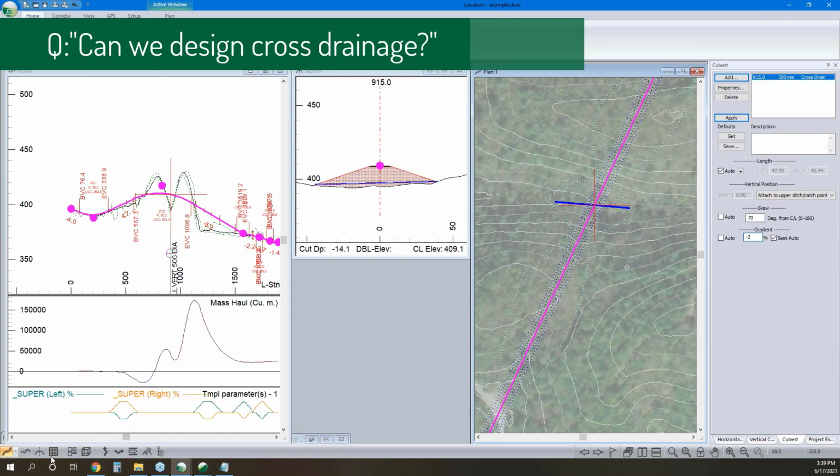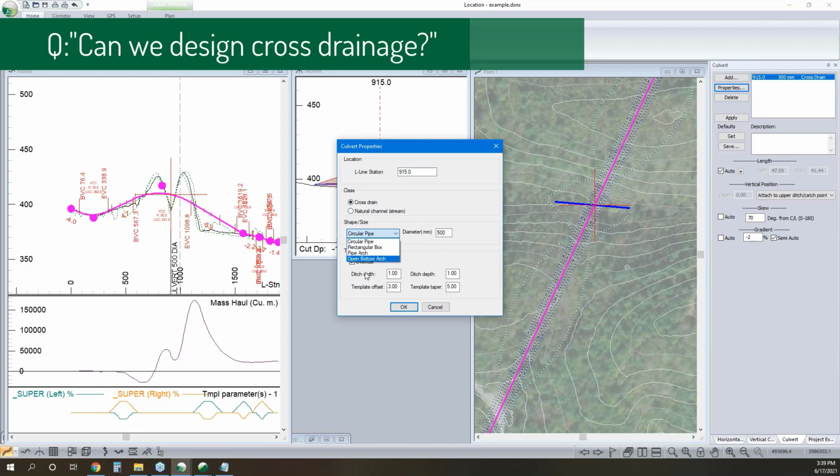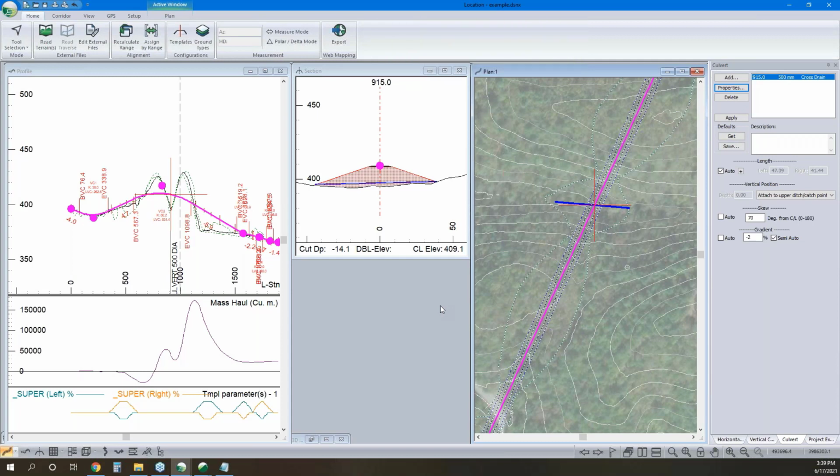And we can also create a data table. Instead of our earthworks, we can have our bill of materials for culverts. You can add as many of those as you'd like. I've got my length auto-calculated based off of my cross-section here. If we want to tabularly set our length, we can. If we want to use a different structure type, we can. If you want to include a sump and override your ditch at the inlet, we absolutely can. So it's meant to be pretty slick.